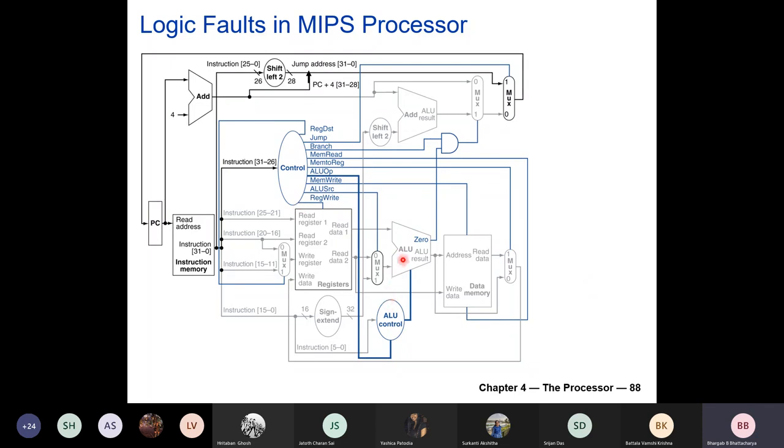You have to throw it away, right? Because this is an integrated circuit, a solid state device. So once the chips are manufactured, it is necessary to test whether they are functioning correctly. And this is very important, because if it fails, it would reduce the yield value, because yield is the percentage of the good chips that are being manufactured, right?